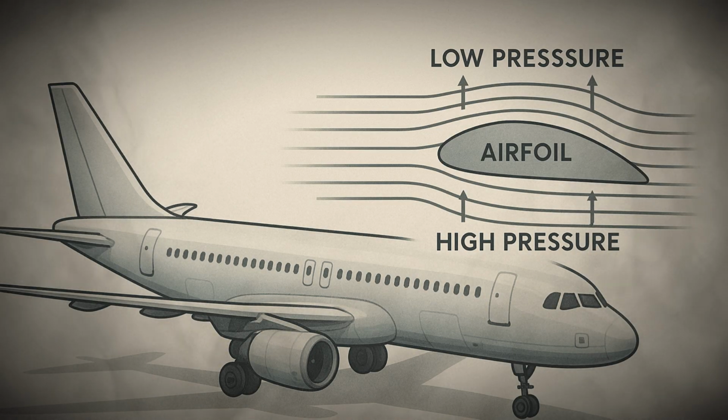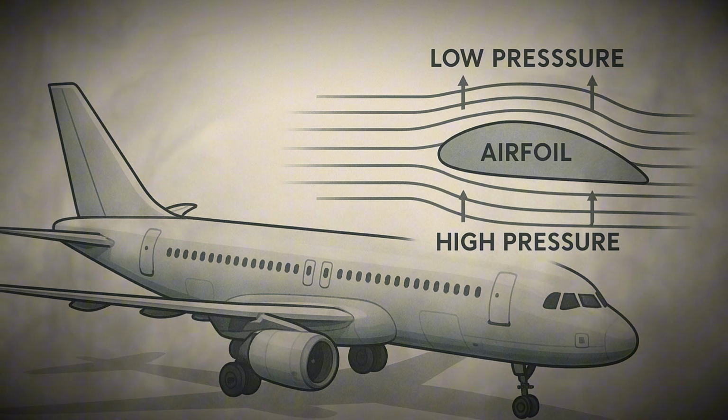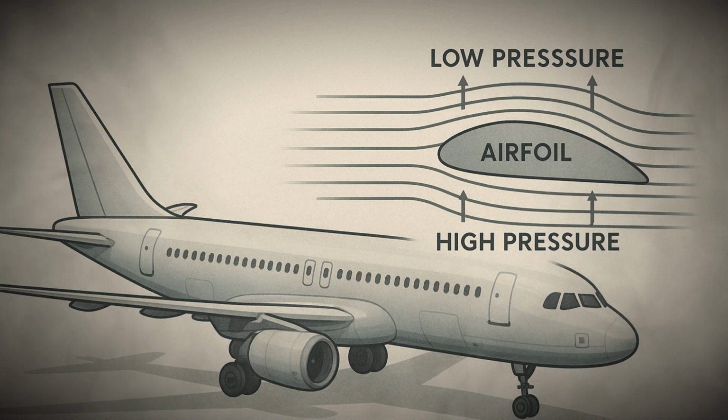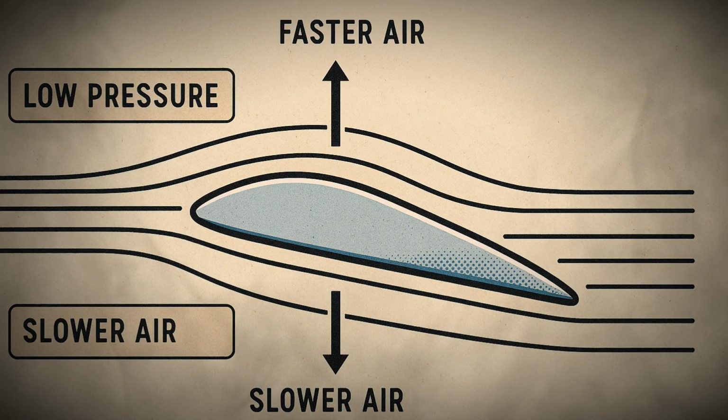The fuselage also accommodates critical systems, including avionics, wiring, and hydraulic lines that connect various parts of the airplane. The structural design of the fuselage must ensure not only aerodynamic efficiency, but also safety and comfort for those on board. It must be strong enough to withstand the stresses of takeoff, flight, and landing, yet light enough to keep fuel consumption low. Advanced materials such as carbon fiber reinforced polymers are increasingly used in fuselage construction because of their excellent strength-to-weight ratio.